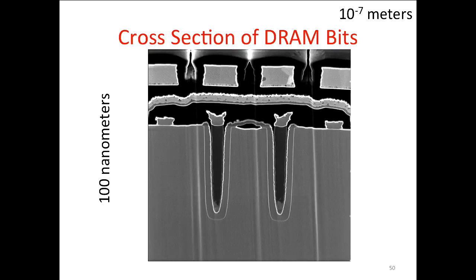It turns out that depends on the temperature, and it takes a lot of power to refresh it like that. So in mobile phones, you actually have a temperature sensor, so they know how hot it is. The hotter it is, the more leakage there is, because the electrons have more energy and can move more easily. So on your phones, it'll have a temperature sensor telling the system how often it needs to refresh. When your phone is cold, it doesn't have to refresh as often, so they can save power. And when it's hot or in your pocket, it's going to refresh more often, so it'll take more power.